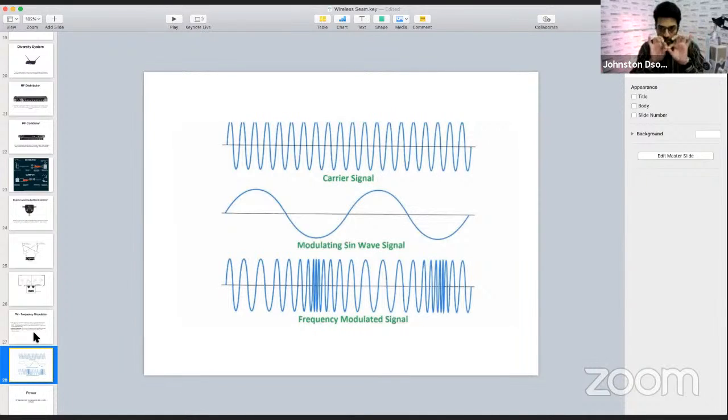The 98.3 FM is called the rest frequency. Whenever you feed audio to it, the modulator will say, okay, higher frequencies, so the 98.3 will start modulating higher, and the frequency starts increasing. And as the audio frequency starts going lower, the carrier signal also will start going lower in frequency. Okay, are you getting an idea of what this is?